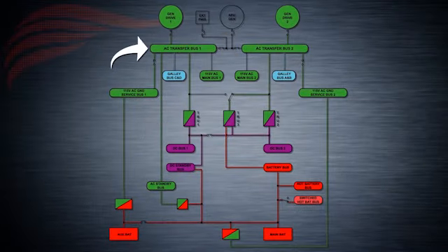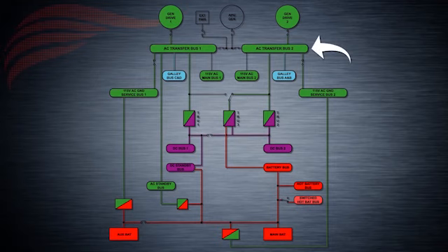TRU-1 gets power from the AC transfer bus 1 and connects directly to the DC bus 1. TRU-2 gets power from the AC transfer bus 2 and connects directly to the DC bus 2. TRU-3 gets power from the AC transfer bus 2 and provides a power source for the battery bus. If power from the AC transfer bus 2 is lost, AC transfer bus 1 may supply backup power to TRU-3 through a relay. The DC system has two batteries, one main battery and one auxiliary battery.